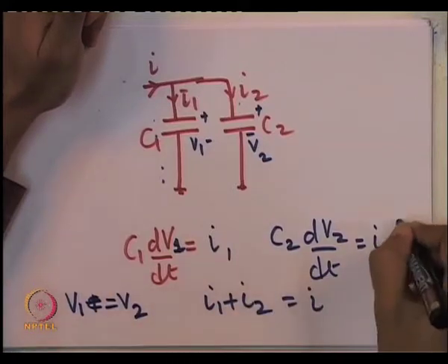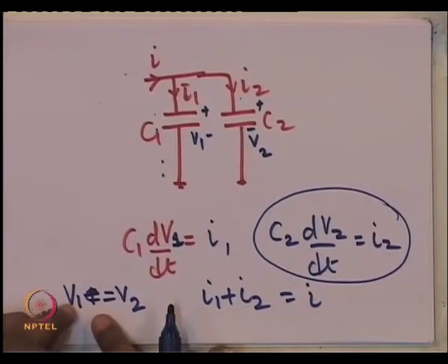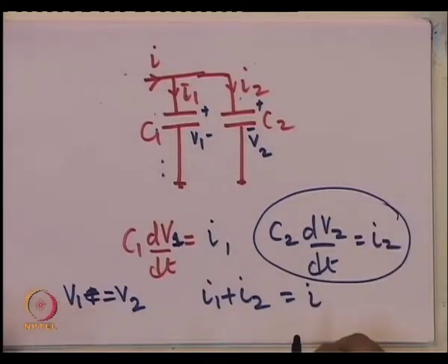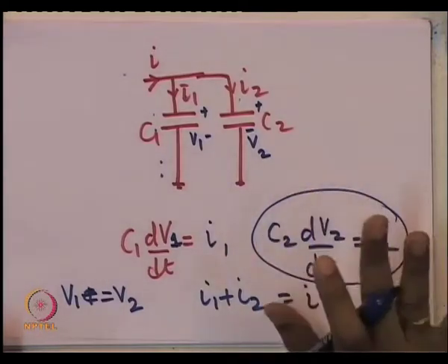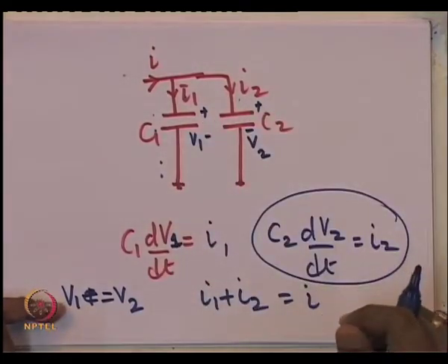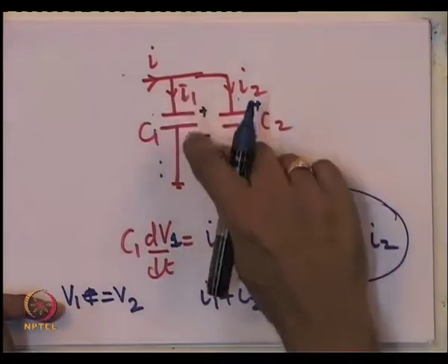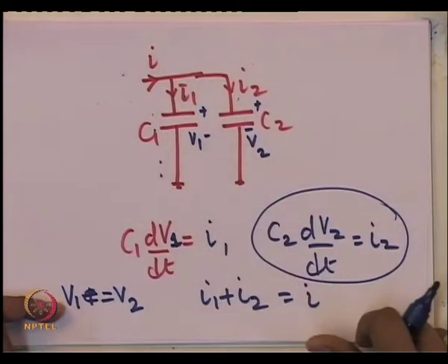So, actually, by choosing V1 equal to V2, why do we require a differential equation again? Why do we need another law to define V2? In some sense V2 is a redundant state in such a situation. So, when you are trying to simulate such a system, it is better to remove the redundant states. You know that V2 is equal to V1, so you only need to determine the current through this. Whatever voltage you have here will be the same as the voltage here.